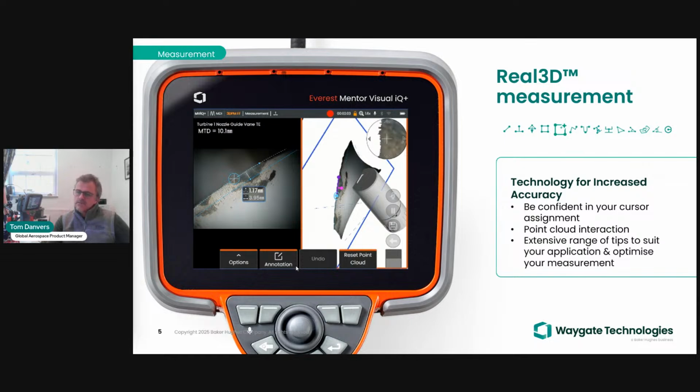And the greatest source of error is ourselves, in as much that it's usually us, because it's not all fully automated. This is a manual process of assigning cursors onto the screen. So where you place your cursors will have a profound effect on the accuracy of your measurement. And so by using Real3D measurement, whether it's the stereo tip or the 3D phase measurement tip, you will have the ability to interrogate that scene using your point cloud. What you see on the right-hand side of the borescope image is the representation of that surface in 3D.